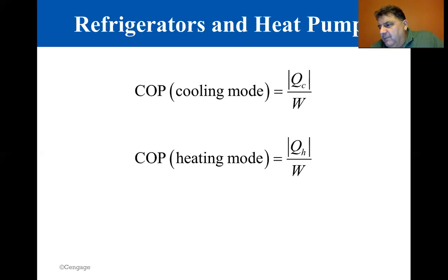In a groundwater heat pump, energy is extracted in the winter from water deep in the ground rather than from the outside air, while energy is delivered to that water in the summer. This strategy increases the year-round efficiency of the heating and cooling unit because the groundwater is at a higher temperature than the air in winter and at a cooler temperature than the air in summer.